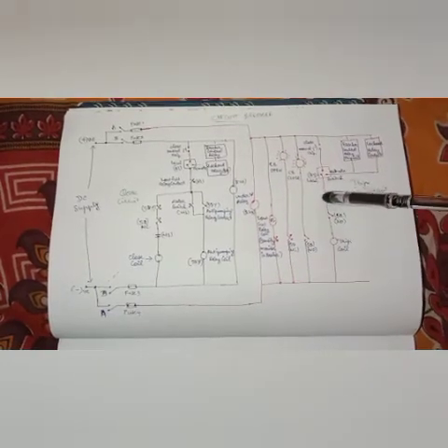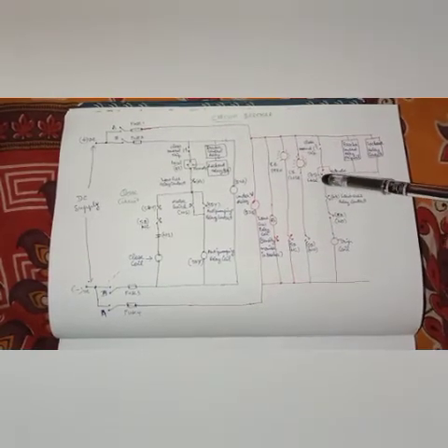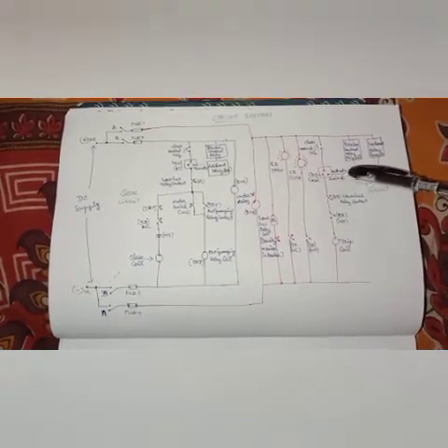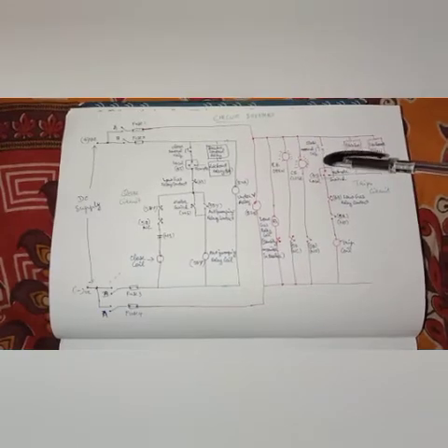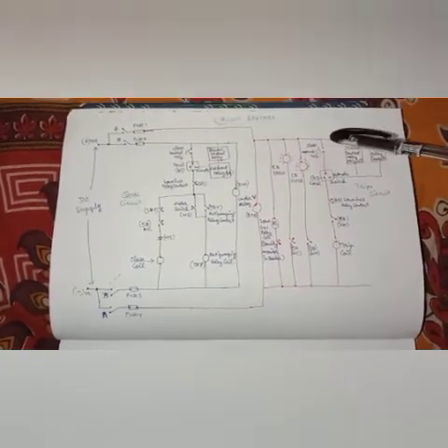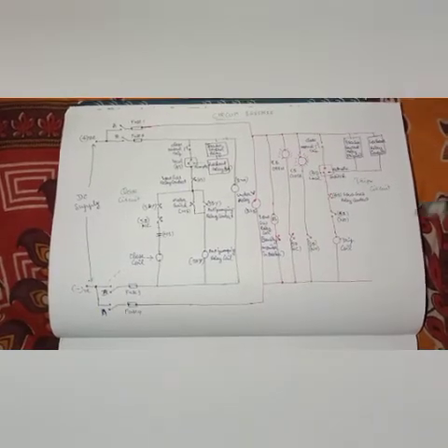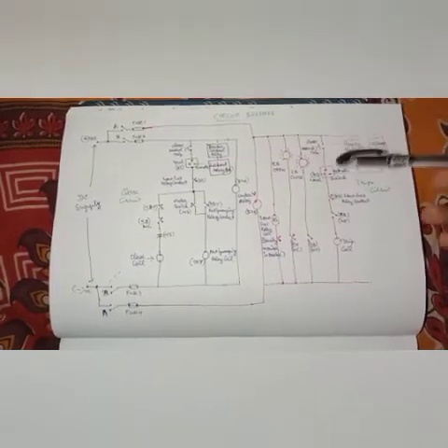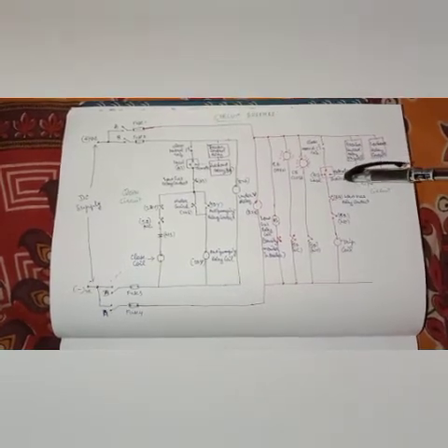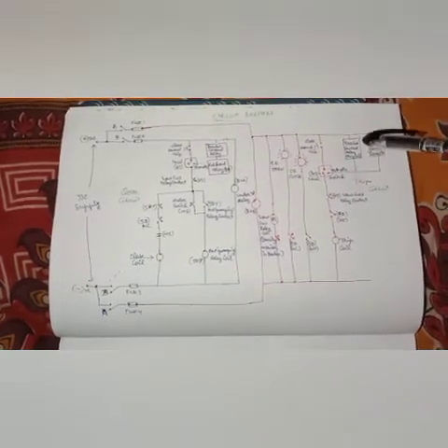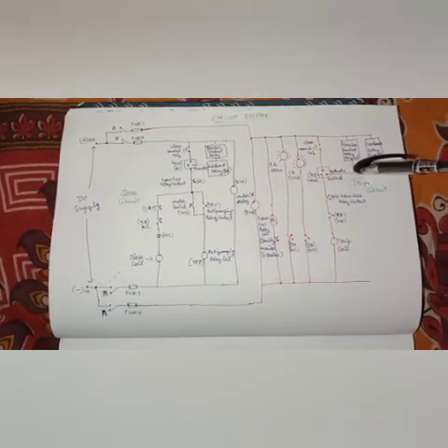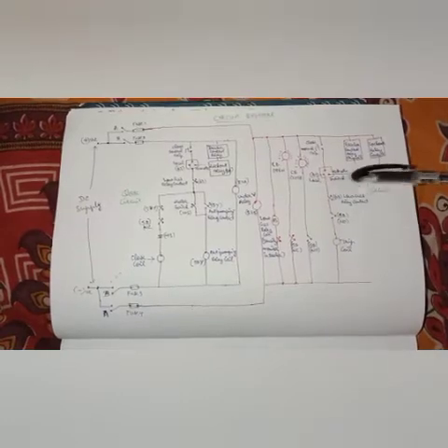So the negative supply will further move to your local switch. Now the breaker is in local, so the negative will move up to the end of your TNC switch. Now we can manually trip the breakers. If we are going with remote condition, from the HMI SCADA the command will be given for a tripping initiation and the tripping is possible.